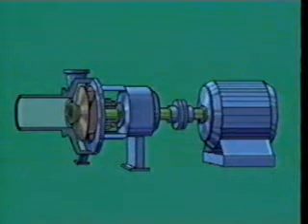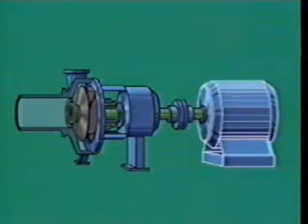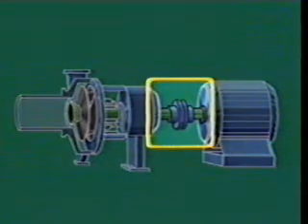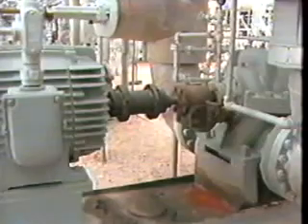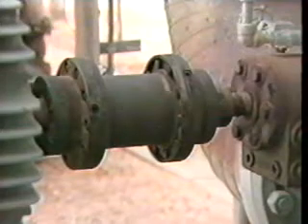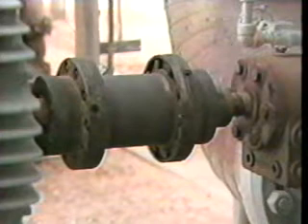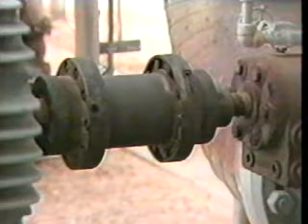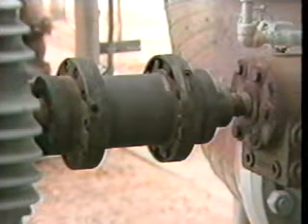Let's stop. Here's the driver. There's the pump itself. What links them? This, the coupling. It connects or couples the driver to the pump, and it does so for a purpose: to transmit power from the drive shaft to the pump shaft. Although they might seem simple, couplings are as critical as all the other components. They've got to be strong enough to withstand sudden changes in the pump's load, and also those times when the driver might stop.